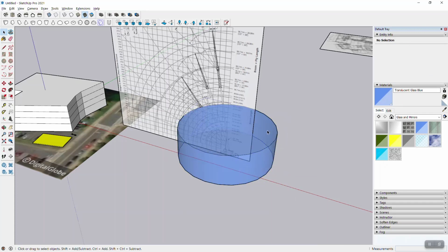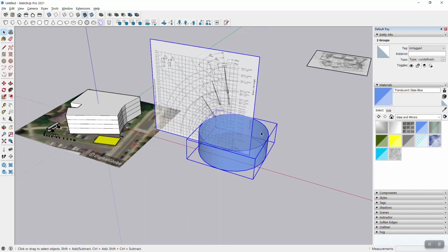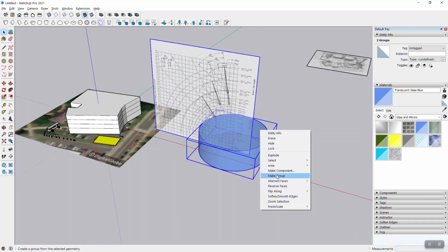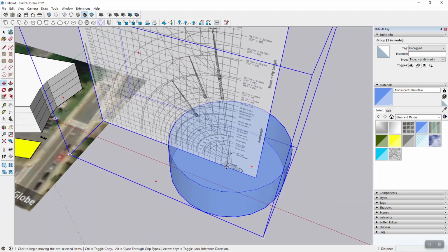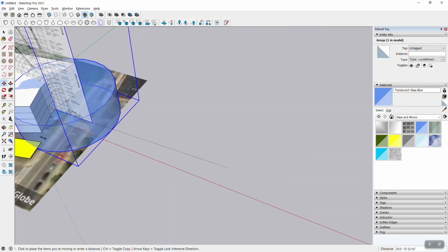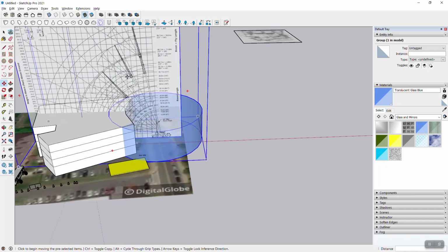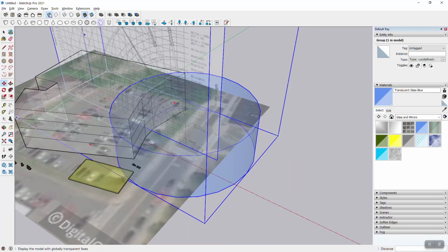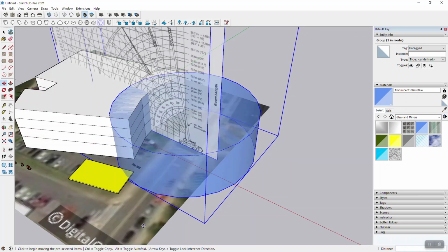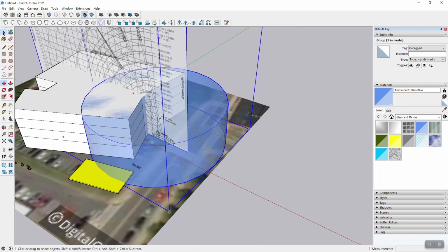Good. So now I'm going to triple click the extrusion that I just created, and I'm going to make a group. And of course, I want to combine that with the diagram, and I'm going to make a new group. And then, of course, you can just go ahead and place that. See that I'm still good here. And now, because you have so many surfaces, it may make sense to go into X-ray mode and align things that way, but you can, of course, use any technique you like.